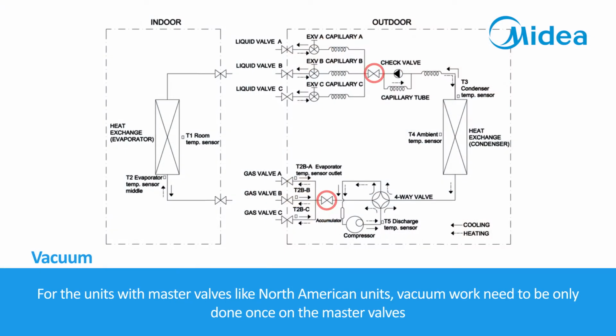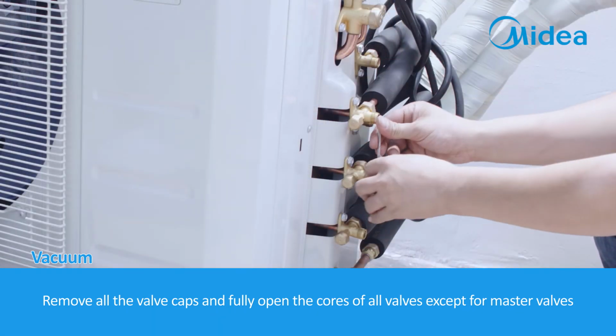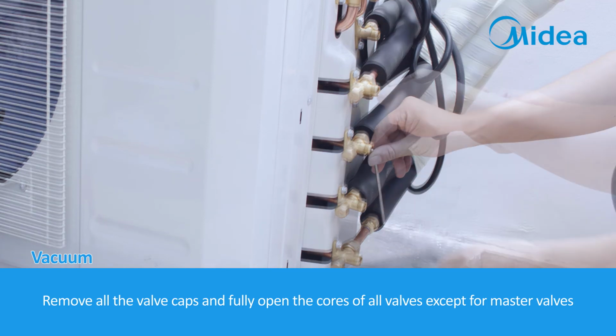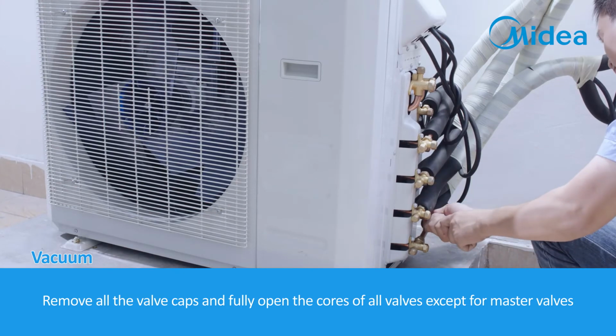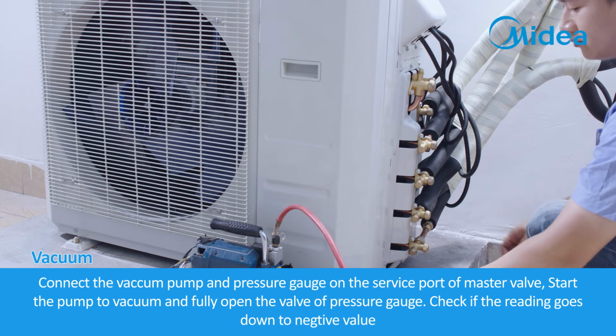For the units with master valves, like North American units, vacuum work need to be only done once on the master valves. Remove all the valve caps and fully open the cores of all valves except for master valves. Connect the vacuum pump and pressure gauge on the service port of master valve.